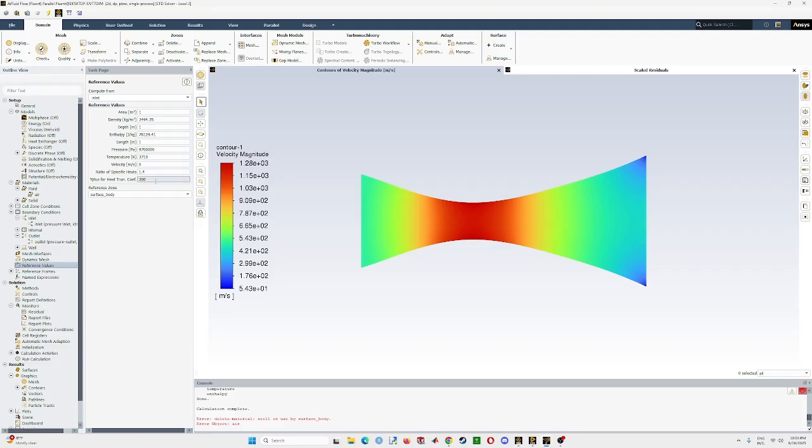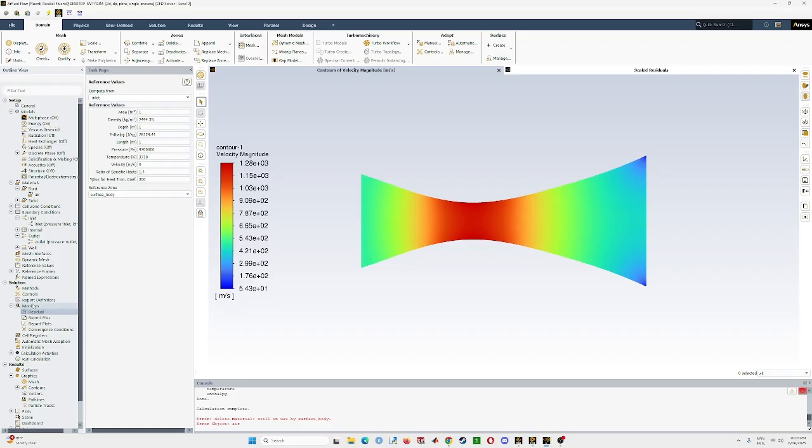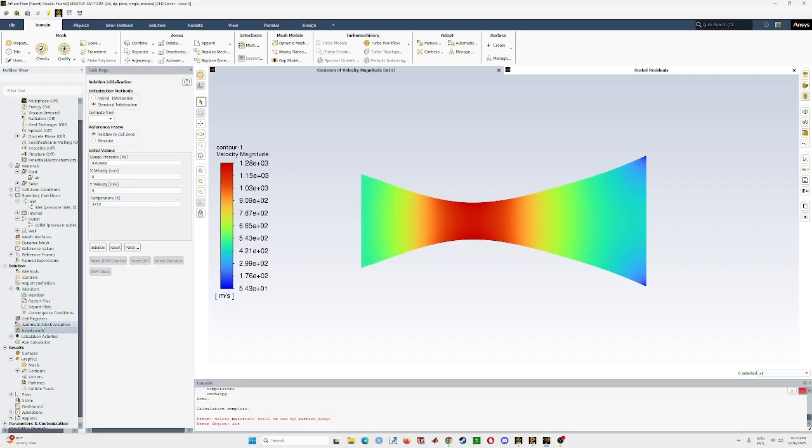You should get all the stuff here that is your inlet conditions that you specified in here, and with the air, they should show up here. And once that was done, I went to the monitors, residual. I changed all of these to be this value. The smaller, typically, the better. And then I went to initialization. I made it standard, compute from the inlet, and there's that. And then after that was all done, I ran the calculation. I won't run the calculation because it takes so long to do.